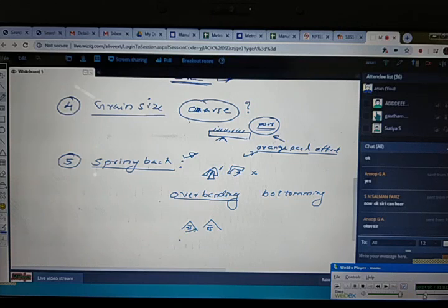Okay, if I decrease that bend angle, what will happen? When it is released, yes, it will come back to its original dimension. Okay, and another one is the bend radius. The bend radius will also be reduced. Next is bottoming. In the case of bottoming, we are applying the force again and again on that particular area to get it overbent. So these are the things to be performed to reduce the spring back. Is it clear to all?